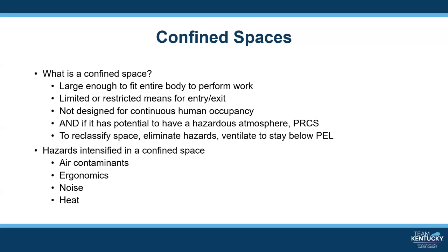In a confined space where welding is occurring, air contamination is of particular concern. Since the space is not designed for continuous human occupancy, it probably does not have doors or windows to open for natural ventilation, and there is probably no mechanical ventilation built into it.